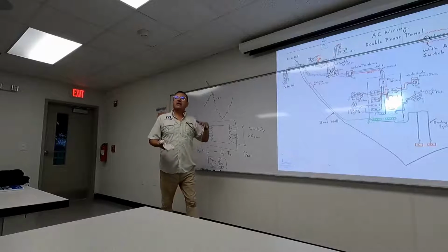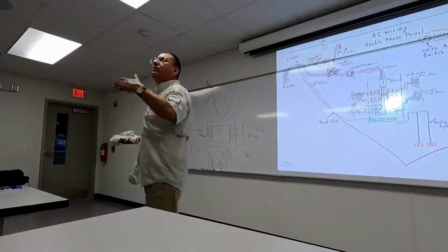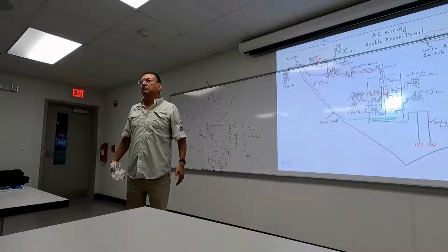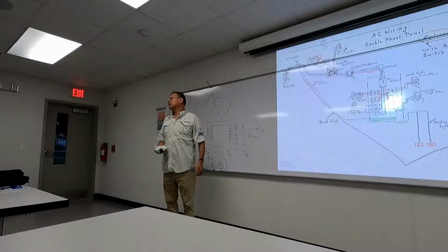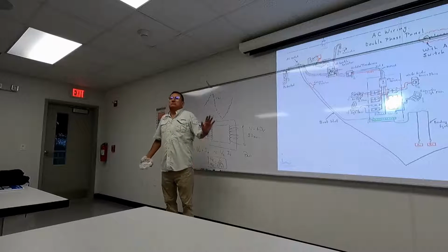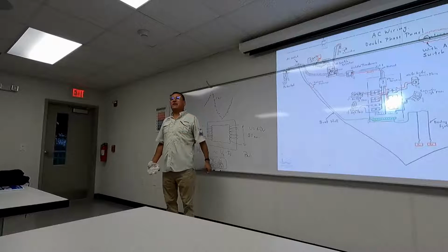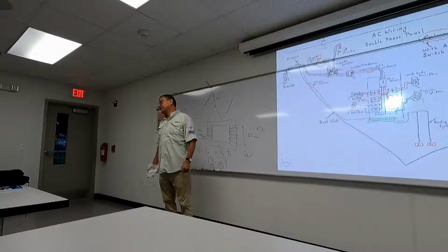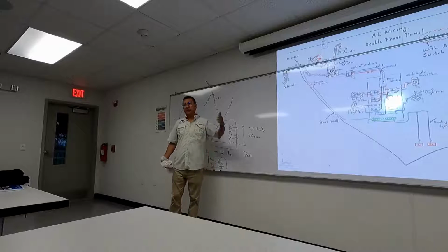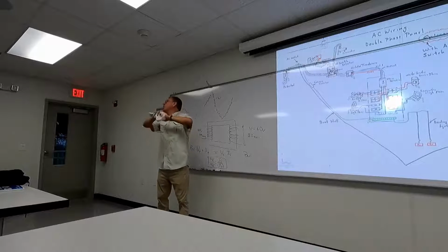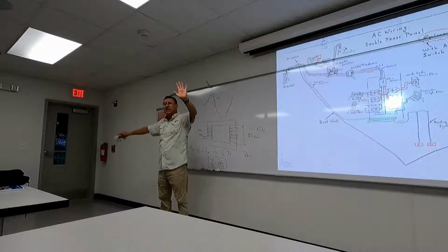Can I wire a boat? Can I use all the equipment, electronic and electrical devices, without an isolation transformer? Yes. Is the isolation transformer mandatory in a boat? No. No. No. Okay? But is the galvanic isolator mandatory, necessary? Yes. Yes. Yes. It's critical in comparison with the other one. Are they similar? No. Nothing. Does one depend on the other one? No. They are completely independent.